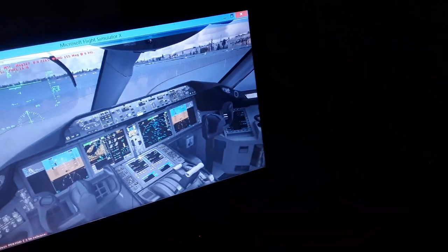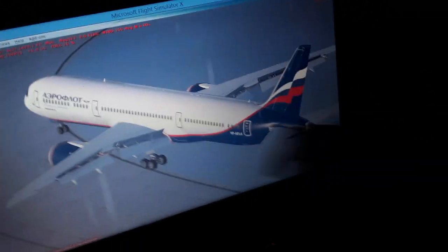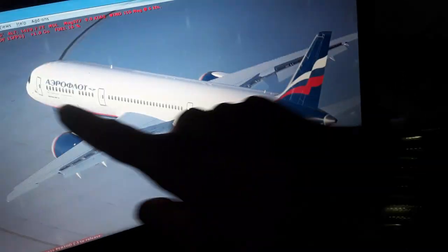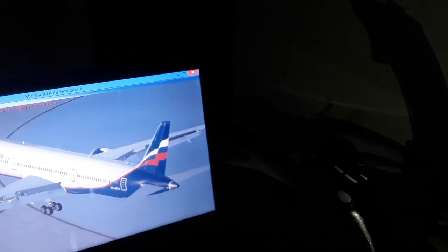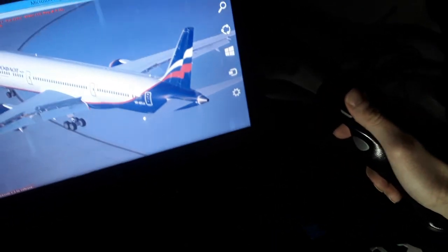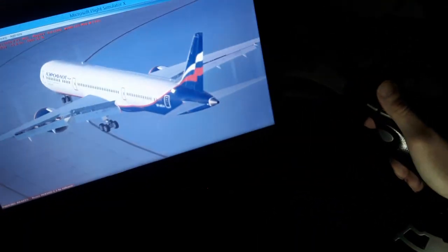And also we have one more axis, the longitudinal axis from the nose to the tail of the aircraft over here. It transverses all other axes. You can make rolling turns. It's the side stick left and right in the Airbus, and it's the control wheel left and right in the Boeing. So it's the same flight controls that you control in all aircraft. You see left and right side stick in the Airbus, ailerons and spoilers left and right.